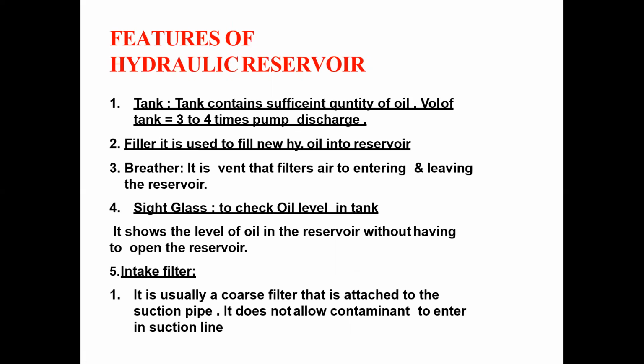The tank contains a sufficient quantity of oil. It is 3 to 4 times the pump discharge. The tank is the place where we are going to store the oil. It should contain sufficient oil so that the total quantity of the tank is 3 to 4 times the pump discharge. The next one is filler.